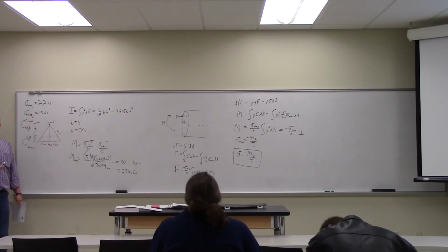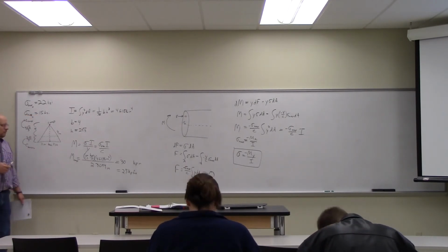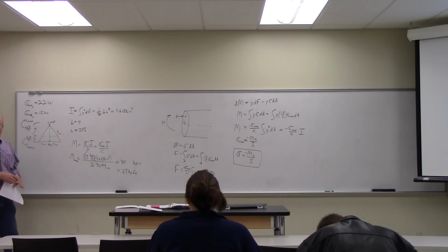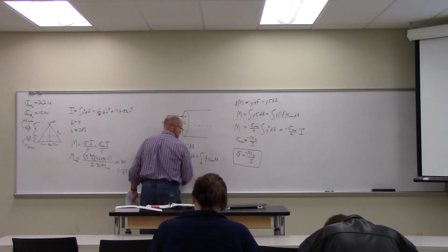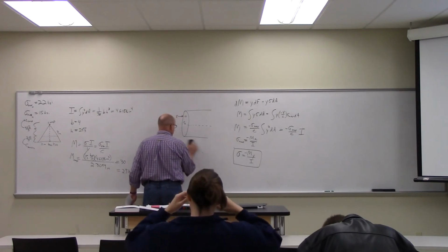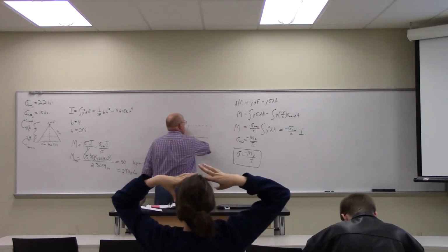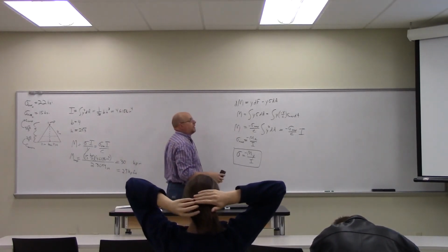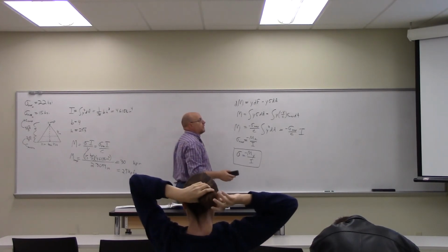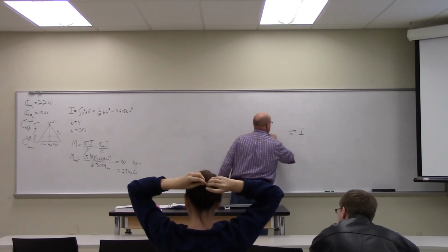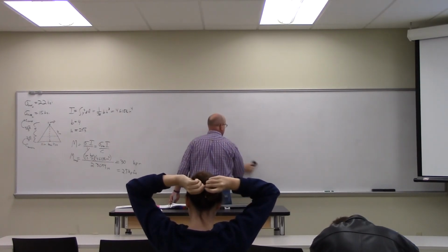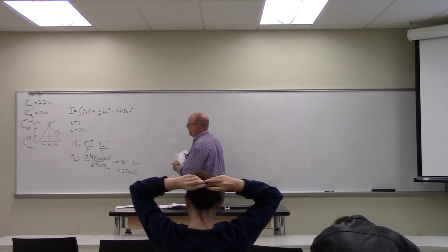Okay? What do I do now? Do I have an answer? Is 2.5 kip feet the maximum moment that can be applied without exceeding the allowable stresses? You don't know until you do the other. Yeah, I don't know until I've done the other side too. I've got to do the tensile side as well.